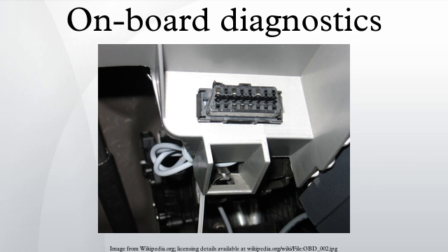ADR 79/01 and 79/02. The ADR 79/01 2005 standard is the Australian equivalent of OBDII. It applies to all vehicles of category M1 and N1 with a gross vehicle weight rating of 3,500 kg or less, registered from new within Australia and produced since January 1, 2006 for petrol-engined cars and since January 1, 2007 for diesel-engined cars. For newly introduced models, the regulation dates applied a year earlier, January 1, 2005 for petrol and January 1, 2006 for diesel.